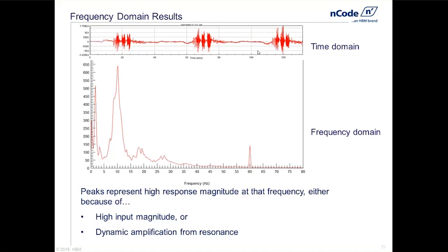If you had turned off all the equipment, you would be able to hear that 60 Hertz hum of the fluorescent lights. So that, in fact, is probably caused by excitation from the surrounding areas causing that structure to vibrate right at 60 Hertz, and not from a resonance. And in fact, if you took this test and then moved to Europe and conducted it there, we might see that this peak would shift over to 50 Hertz.